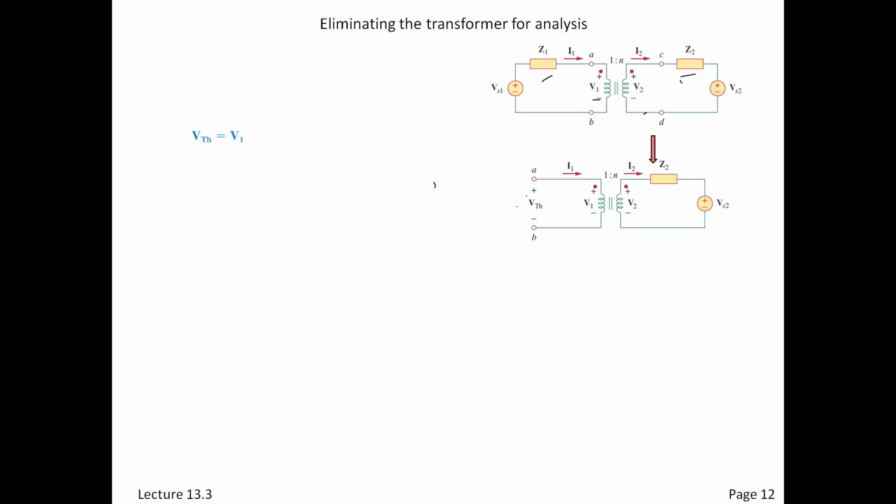All right, the Thevenin voltage is V1, and that's V2 over N. Why? Because we've got a simple reflection coming in, right? It's V2 now. Let me just point out, don't get confused. This is V2, this is V1, right? This over here is something else, VS2. All right, we're claiming now that that's VS2. The only way that can be true is if I1 is 0, right? Otherwise, you'd have a drop on the load.